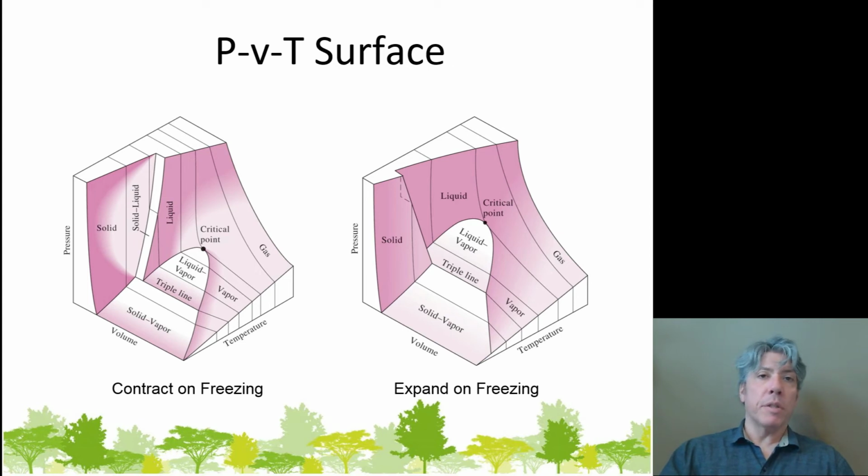The problem with geothermal is that you have to put a big heat exchanger in the ground, and regardless of how you do it, it ends up being relatively expensive. It's usually the most expensive part of the installation, easily costing $20,000, especially if you go with vertical boreholes and a nice vertical loop system, so you can access temperatures well into the earth. Well, on the scale of the earth, barely into the earth, but still 200 feet down or so is a pretty good distance, I guess. That's a problem. Well, the sun still shines in the summer. Is there something else we could put thermal energy into? Turns out there is. I have not looked into this much yet, but it's something I'd like to play around with.